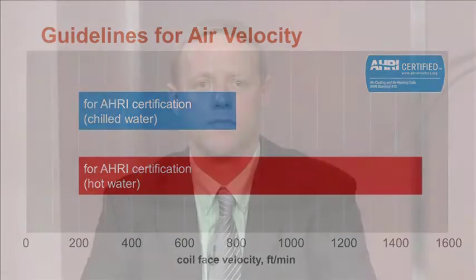In most applications, the cooling coil also dehumidifies as water vapor in the air condenses on the cold fin surfaces. The water then drains down the coil surface, drops into the drain pan located beneath the coil, and is piped away by the condensate drain line.